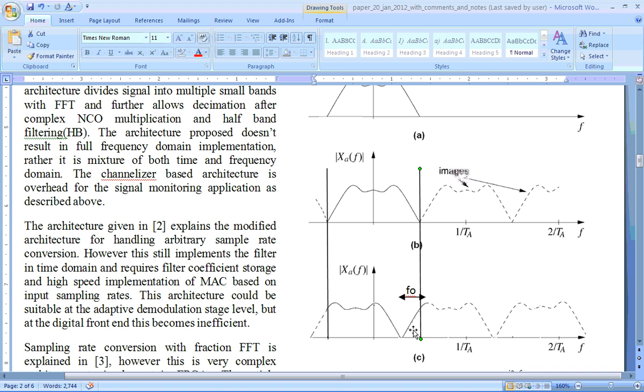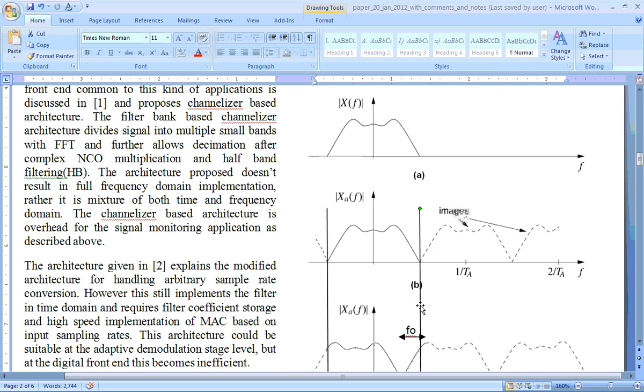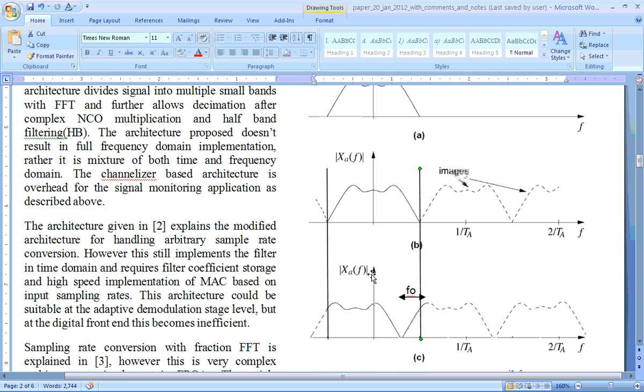So when you do FFT in your FPGA, the FFT bins that you have are from here to here, isn't it? Let's say you are doing a 1024 point FFT, that 0 to 1023, whatever you see here, are nothing but the values over here. For clarity, we interpolate those points and plot one continuous curve. But we know the FFT output is not this continuous curve.